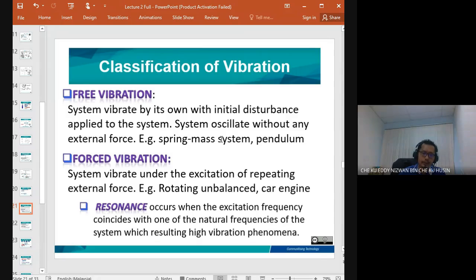And then we go to forced vibration. Forced vibration is the condition when there is an external force induced to the system. That commonly happens in industry applications, when there is machinery in running condition. Any rotating machinery can produce harmonic excitation, such as rotating unbalance. If there is rotating equipment, the unbalance can produce an unbalance force. And even every component, the gear, the bearing, all of that induces what we call a harmonic force.